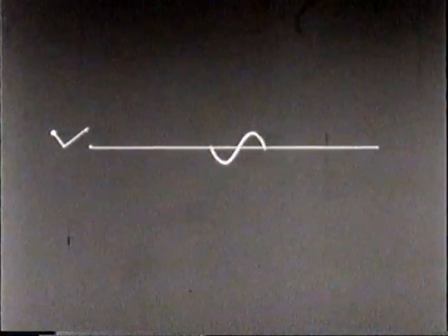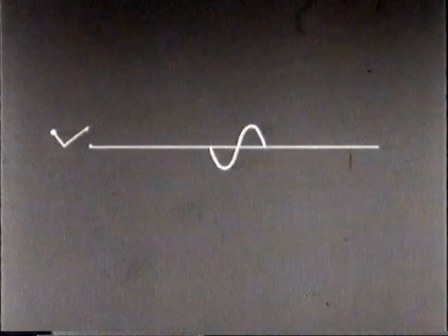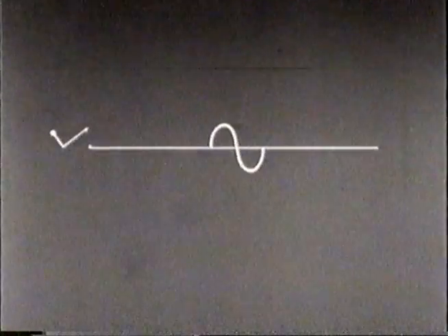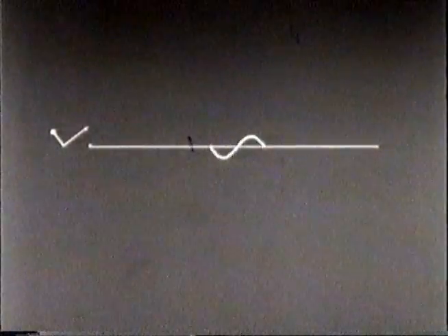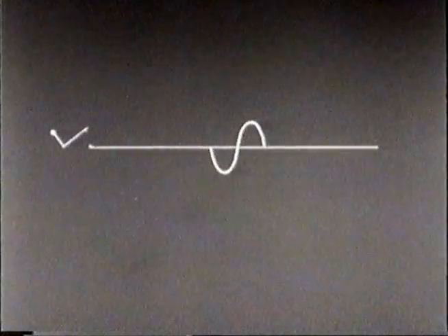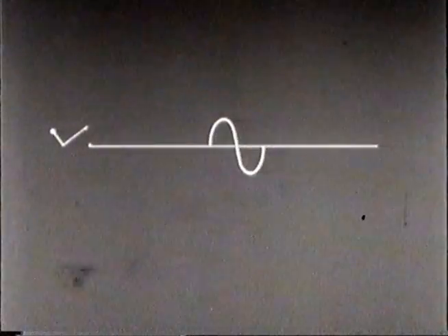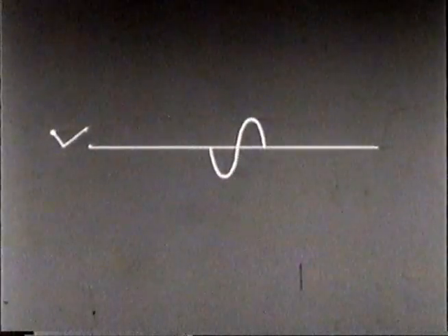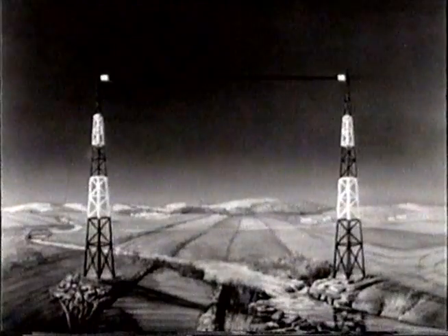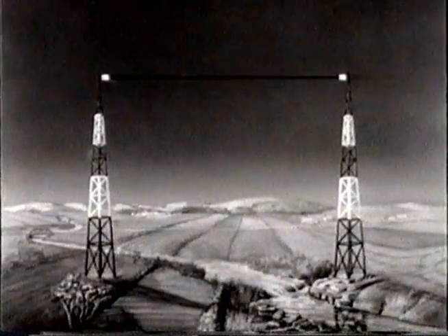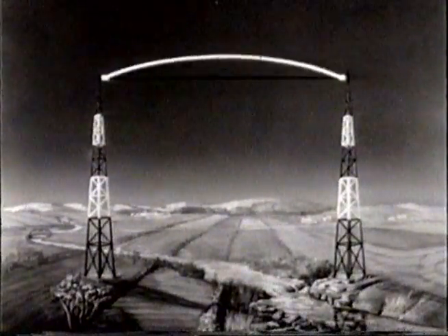A standing wave does not move along its conductor, but continues to oscillate in one position. If energy is supplied at the periodic frequency of the standing wave, it will oscillate indefinitely. A complete standing wave consists of two opposing peaks of electric energy. A half-wave antenna resonates at the frequency and wavelength of half of a standing wave.